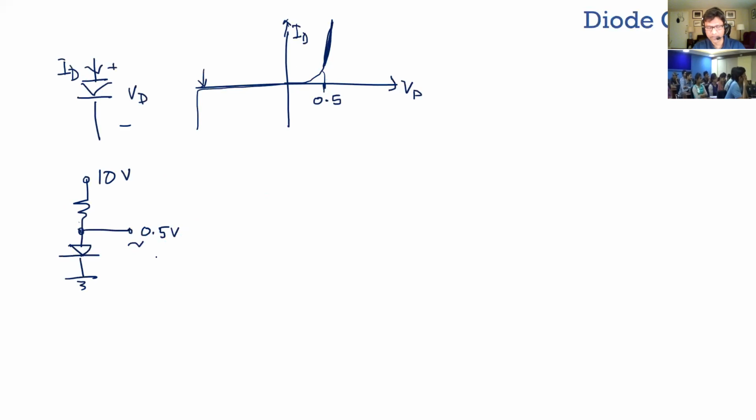If I tell you to find out exactly, I have to give you all the diode parameters. But typically, if somebody is asking you diode circuits for digital circuits, it is assumed that if there is any current flowing through it, the voltage is automatically 0.5 or 0.7, whatever they've given you. So let's say this was 10K, and I ask you what's the current flowing through this?